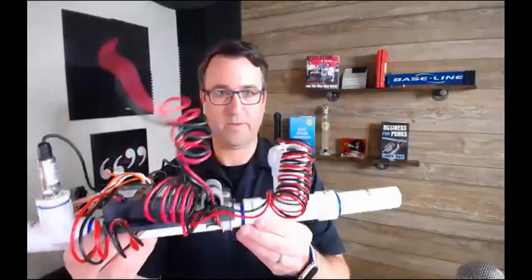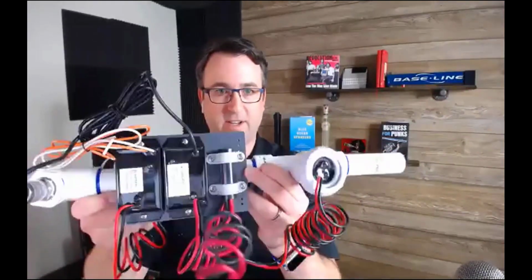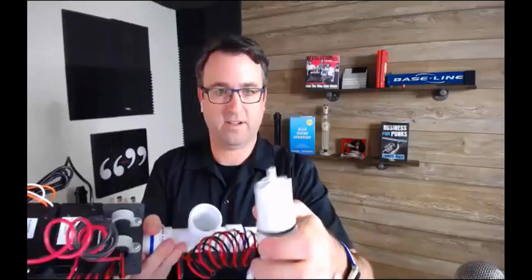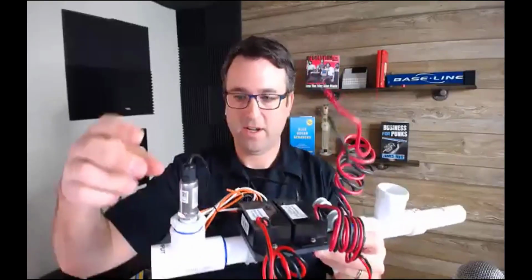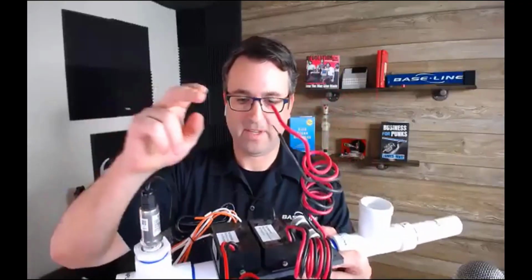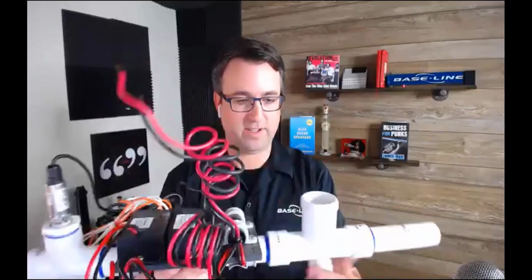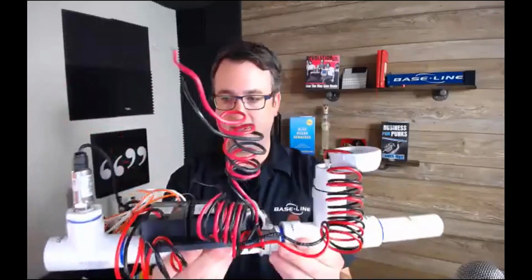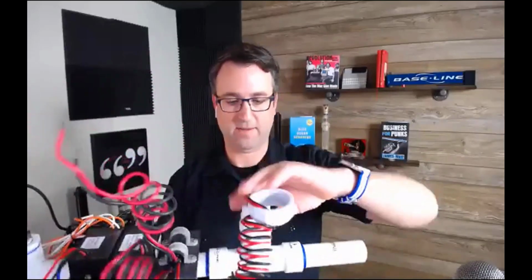So this is what we call a control point. Let me turn it this way, which consists of the flow sensor. Let's see if I can pull it out here. Flow sensor with the paddle wheel. Nice. And then also on our control point, I'll just mention that we have our pressure sensor and then the master valve decoder. So the control point is an all-in-one device that allows you to read all of these data points, pre-configured from the factory, all in one. Right. So then this here, I've got just that portion of it, just the flow sensor that's in there.